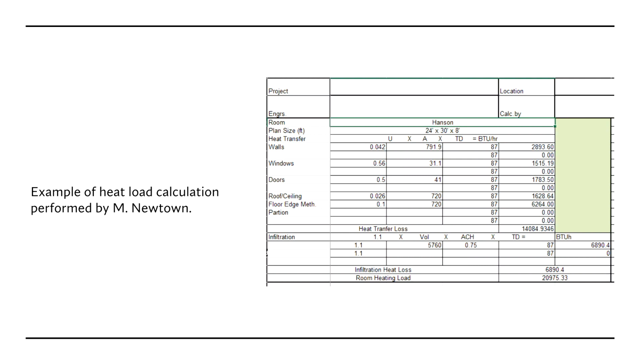But we're looking at the U value, or the inverse of the R value, which is like the insulation value. The resistance to energy flow is the R; the U is the rate of flow. Then the area and our temperature difference. In this case, it's 87 degrees. We like to pick our design temperature for Northern New York. It depends on which part of the energy code you're looking at, and also in Northern New York, really which part of the region you're in. Canton is minus 9 degrees Fahrenheit as the design outdoor temperature, and we like to design indoor for 72.